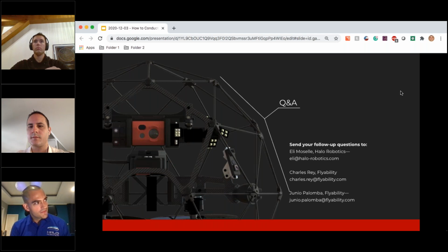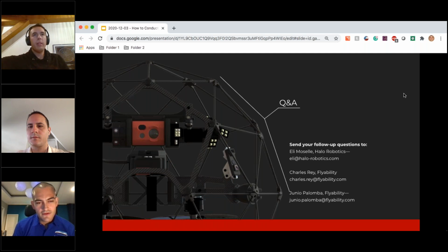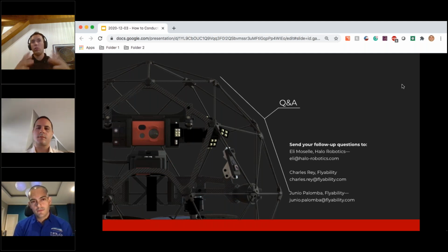Charles, do you have anything on this subject? Yeah, there are a couple of things that have been done in the past. We used a good old fishing line and a hook at the end when we fly in a silo. That is a good way to recover a drone if it's right under yourself. What we did a couple of times too, which is an interesting method, is we fixed a fishing line and a hook under a drone, and we flew that drone over the other drone that was stuck, and then we took back the drone like that.